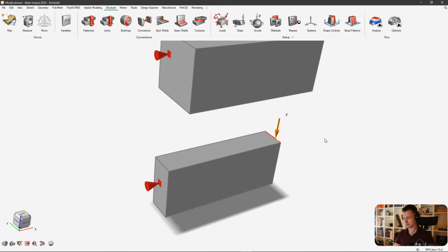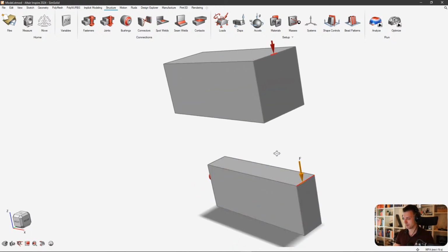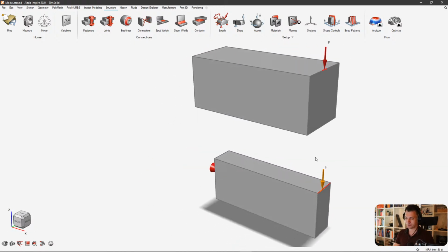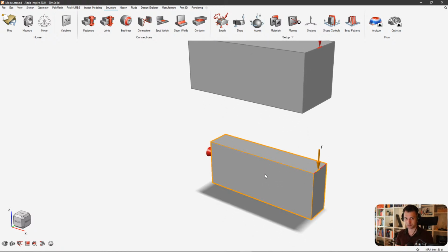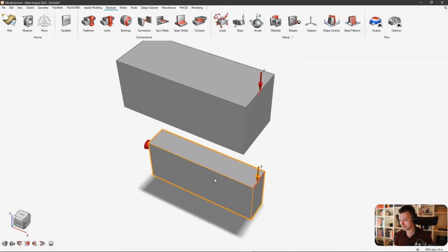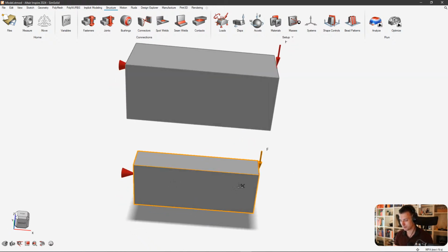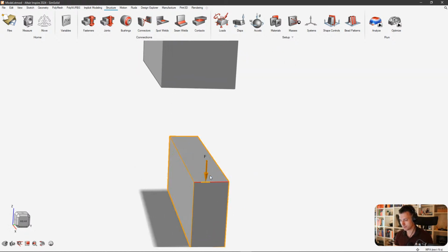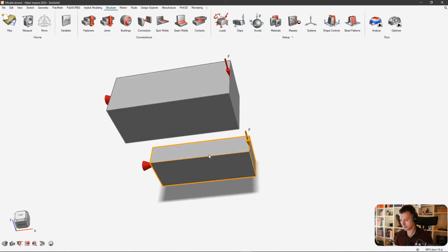There's also something, it's a point a lot of guys miss. If you do a symmetry constraint, you also have to decrease the load accordingly. Because if you just think you have half the structure, that means half the stiffness, and you put the same amount of load, you get double the displacement, and that's not what you wanted. So bear in mind that if you do a symmetry constraint, then you have to look at the loads. It gets even more complicated, to be honest, if you're talking about a multiple point constraint, MPCs. Because where should the master node of the MPC be with symmetric loading? It's not that easy.